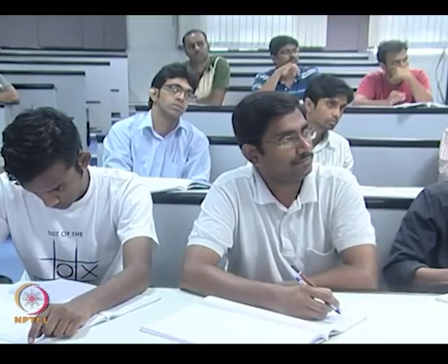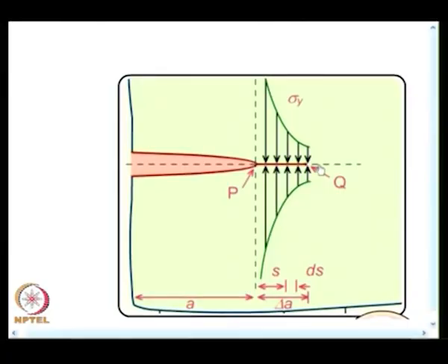Okay. So, in order to visualize that aspect only, the animation was done. Now, for writing Q, you will have to imagine that there was a longer crack like this and find out what is the displacement. Writing P is very simple. This illustration is quite sufficient for you to write what is sigma y variation. Only to recognize the displacement, you have to imagine that there was a longer crack and you should use the value of theta and r appropriately and get the expression.